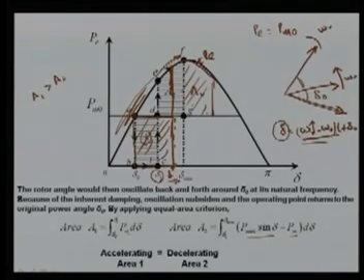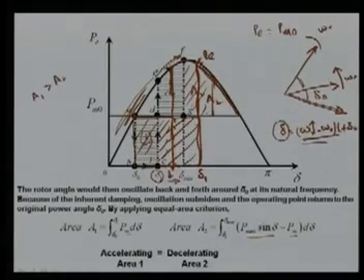Let's suppose you have increased further, so your delta 1, your fault is cleared after a longer time. So this area now reaches here, and now you have gone here, and again you can see this bounded area A2 is now less than your area A1. This area here is larger than this. So in this case your A1 is more than A2 and the system will be unstable.